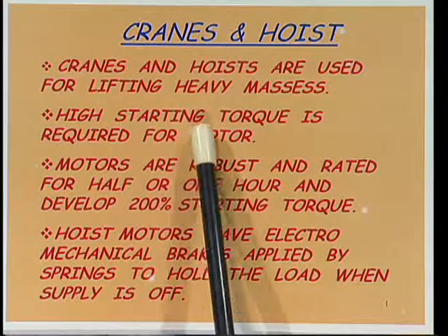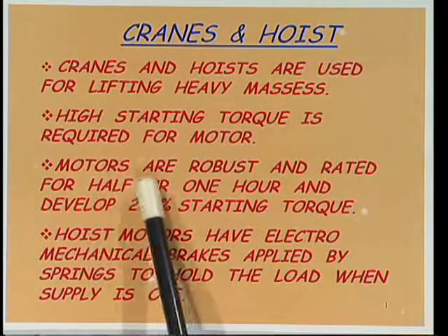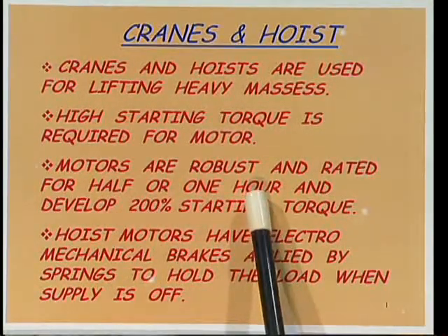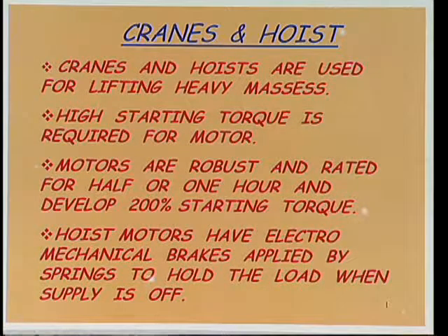For these cranes and hoists, the motor used should have very high starting torque. Motors are robust and rated for half an hour or 1 hour, and develop 200% starting torque.